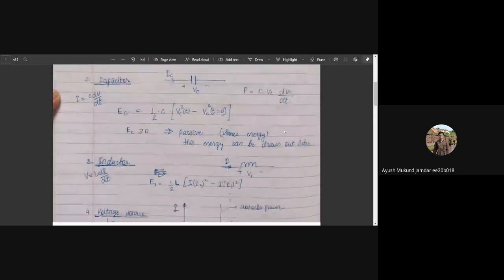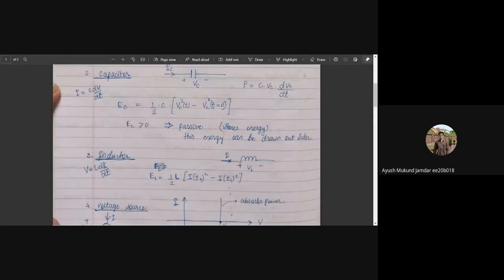And the final circuit element that, apart from the voltage and current sources, of course, is the inductor. Inductor, again, as we all might know, it works on magnetic energy. So it works on change in flux. So when rate of change of flux is EMF, so from that we get V is L di by dt. So when current across the inductor increases, di by dt will be positive. Since the inductor will try to oppose a change in its flux, which is L times I, it will try to oppose the change in flux.